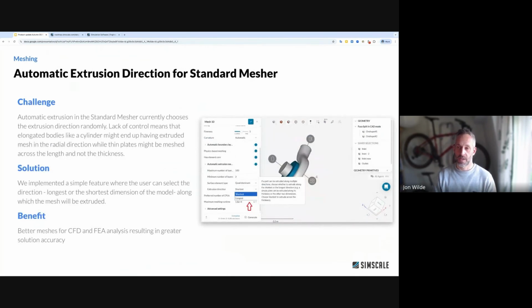And then within meshing, we have automatic extrusion detection. So if you're modeling a long pipe, you don't need to waste mesh on the normal kind of randomized mesh inside a pipe. It's not very efficient. It's also probably less accurate if the flow is totally linear. What you can do is say, okay, I've got an extrusion here, just extrude the mesh through that pipe. But now within SimScale as well, you can automatically do that. So it will search the model for you, figure out where extruded meshes can exist, and then apply them for you.